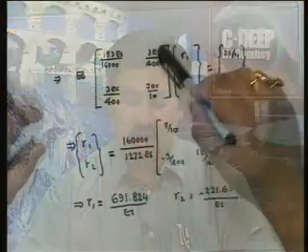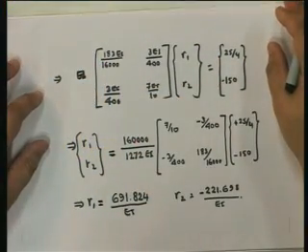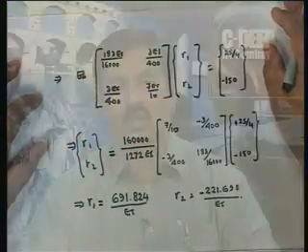Now, by the Maxwell-Betti reciprocity theorem, you know that the force load at one point that gives a displacement at another point is the same as the load at the second point giving the same displacement at the first point. And this is essentially because of that reason. Remember, when we were using the force method, we got that the flexibility coefficients were the same. Well, these are what are known as stiffness coefficients.